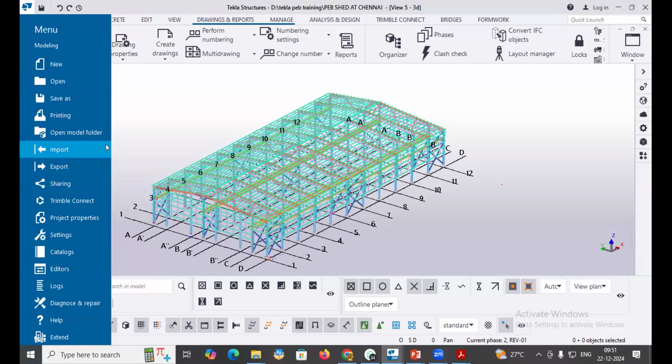You can get not only the exact value of the project, but at least a nearer one, with only 2 to 3% variation, because while applying connections you will be adding stiffeners and bolt weight, and another set of connections, or any corrections in the model. Only in that way will the weightage differ; otherwise you won't get a tonnage-level difference. So for estimation purposes you can use this easily, and you can work this way to get the project bid without giving the total working pattern for the project.